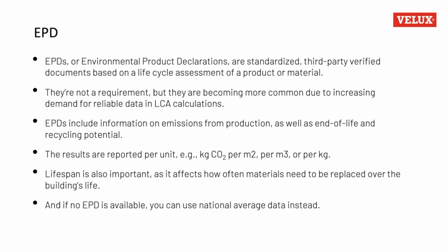But if you look to DGNB sustainability certification, then there's a benefit of using product-specific EPDs compared to generic, because you have a small penalty for using the generic data. Yeah, exactly. But of course, in different design stages, maybe in the early stages it's easier to use generic data, and then later on you can begin to look at more product-specific data and therefore also get a more accurate LCA result.